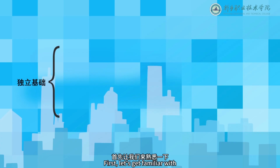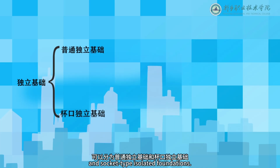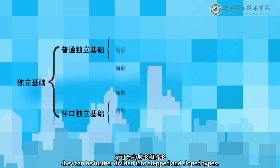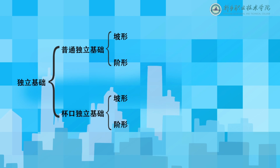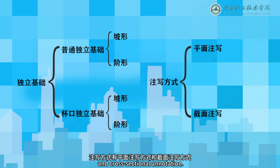First, let's get familiar with plan notation for isolated foundations. Isolated foundations can be divided into conventional isolated foundations and socket-type isolated foundations. According to the cross-sectional shape of their foundation slabs, they can be further divided into stepped and sloped types. The annotation methods include plan annotation and cross-sectional annotation.